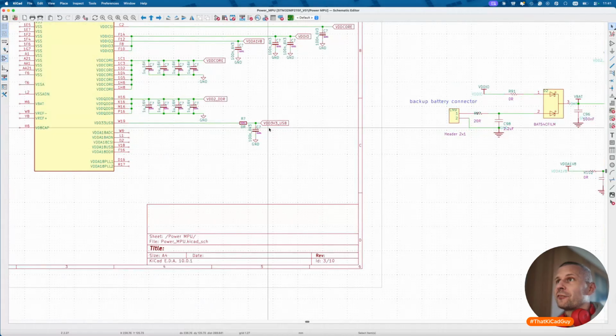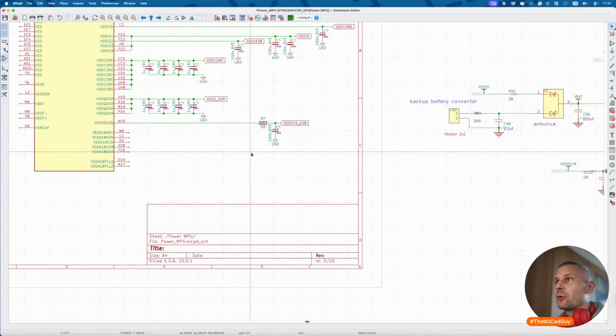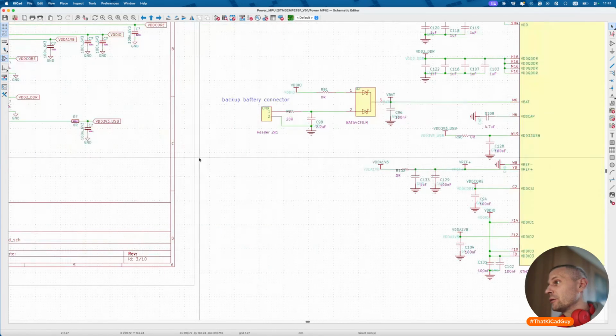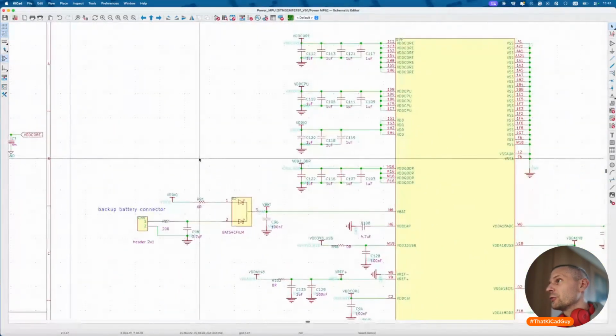So I said to myself that day, it was the last time I am using such small components, only 0402 and higher and bigger, because it's not possible to manually solder it.